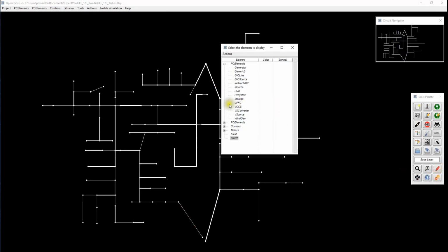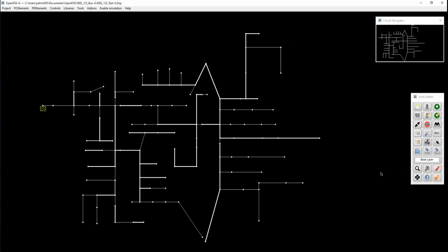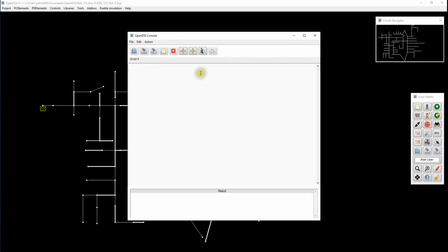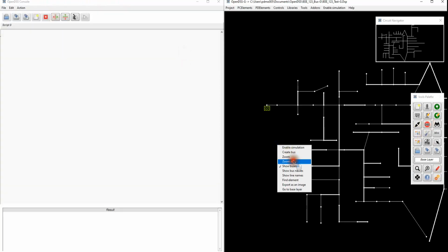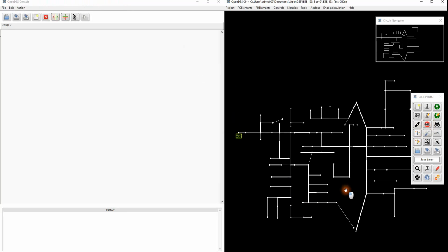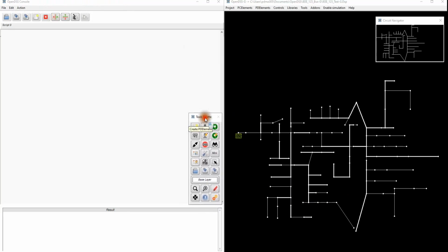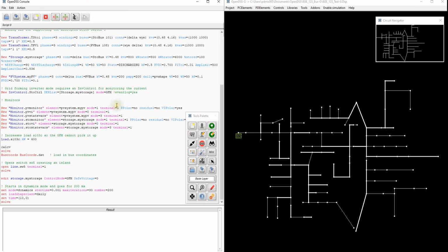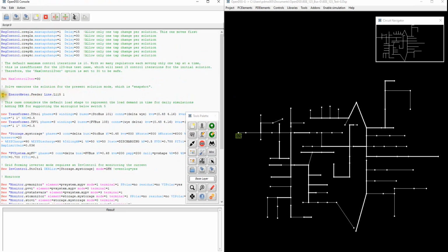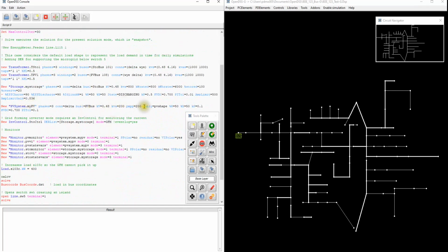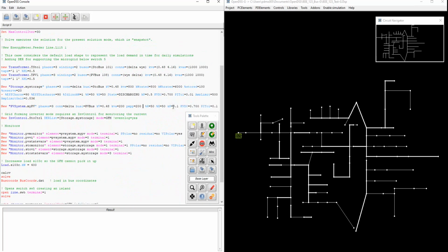For the next demonstration, I'm going to bring the IEEE 123 node test system, and I'm going to demonstrate some other widgets. In this case, I'm going to use dynamic simulations for that purpose. What I'm going to do is I'm going to use the DSS-G scripting panel for adding a storage device and a PV system. Then what we're going to do is we're going to open one of the switches of the 123 bus test system, and we're going to operate the system as a microgrid.